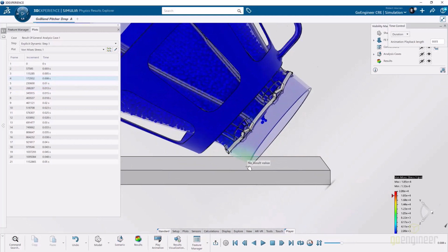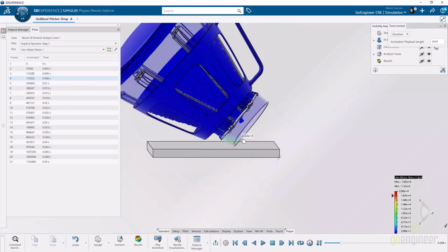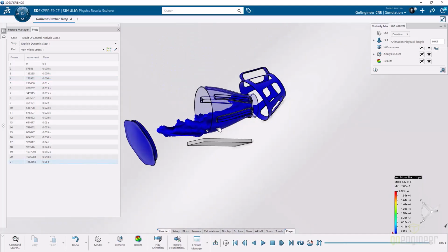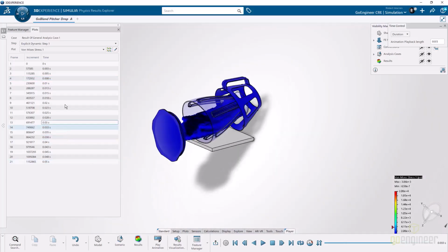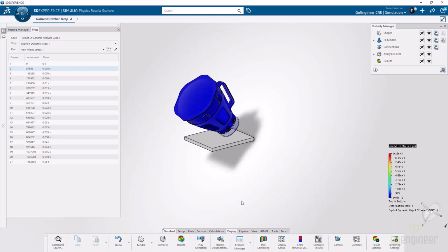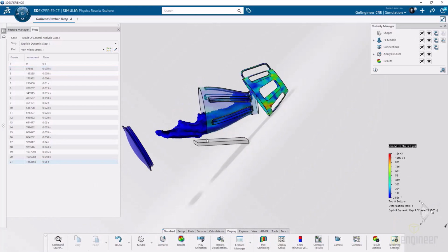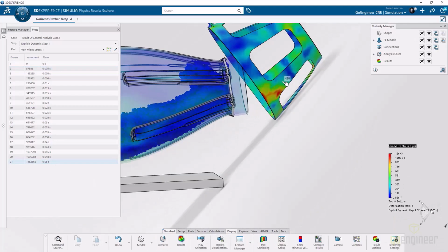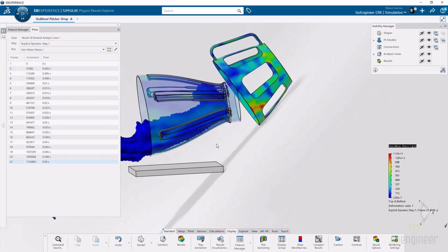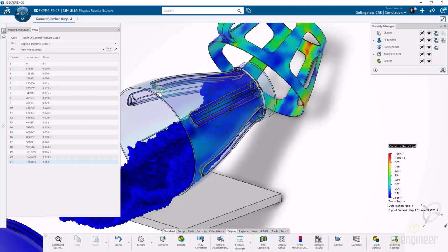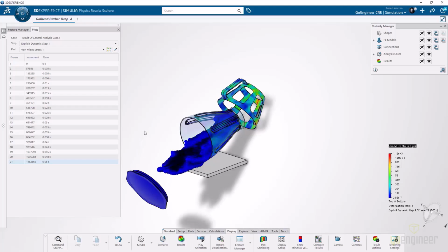Now we can see more than just, hey, we're going to spill the liquid. We can look at things like stress on the pitcher. How does this compare to the maximum stress that the polycarbonate would be able to see, right? Are we going to be cracking the polycarbonate during this drop? What is the stress on the basket itself? Is that within what the nylon can withstand? Kind of understand what the pitcher looks like.